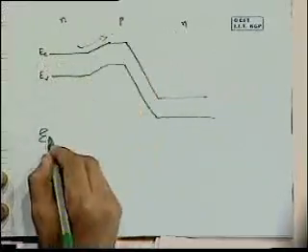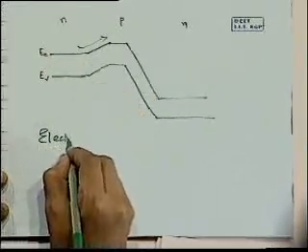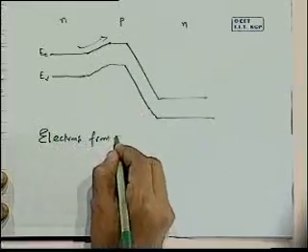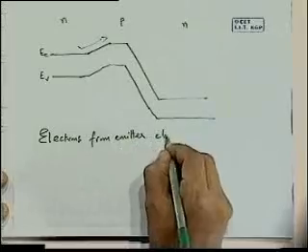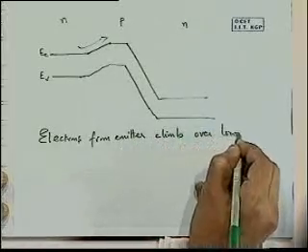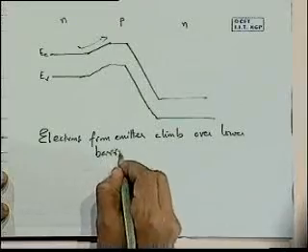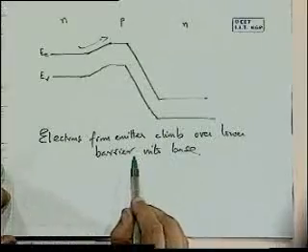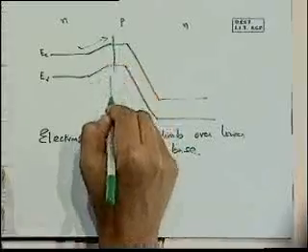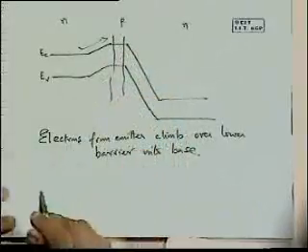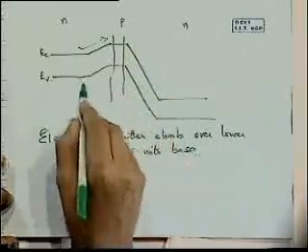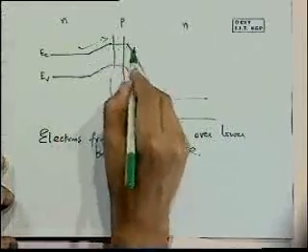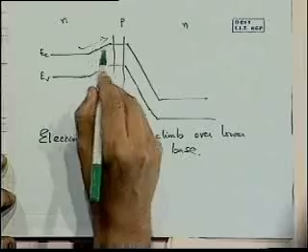So we have this in forward bias. So from equilibrium now it's easy. Electrons from the emitter climb over the lower barrier and enter into the base. Now here is the thing: in the base, I said that the base is lightly doped as well as very thin. And here are the reasons for that. The base is going to be very narrow, the region through which the electron will go before it hits the space charge layer on this side. And so it's climbed here, and through a very narrow region of the base, it's going to have to pass.